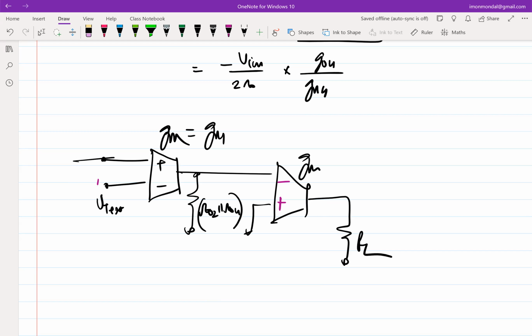So now you see that this stage need not be another differential amplifier then, because the requirement of having two identical input stages has gone away. The plus and the minus terminals did not have infinite DC impedance. Okay, so can you suggest an option of implementing this second stage GM using a transistor equivalent? Common source amplifier, not common gate, common source amplifier.